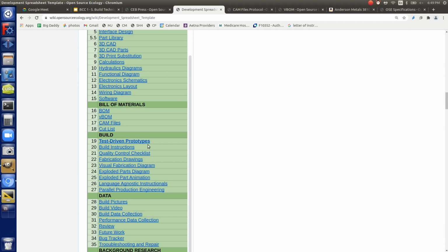For the next build, we say, well, next time we'll make sure we add more blocks to the foundation there. Or do the flat pad and that's finely graded. So quality control point: take a long level and measure that your floor is flat and doesn't have a quarter inch bow. You literally had a quarter inch space underneath it when you spanned across the module with a 6 foot level. Great, quality control point.